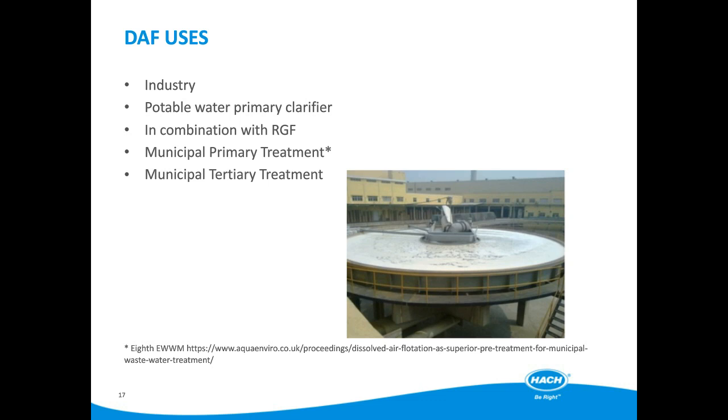During this latter trial, several arrangements were tried, initially with the DAF located after the primary settling tank, and then with the DAF receiving screened sewage. Other options were operating the DAF on air only, and then adding coagulant and polymer. The stated high removal rate of total phosphorus is not surprising given the combination of the solids removal rate and the addition of ferric chloride, which would chemically react with any soluble phosphorus present. But more information on this is available at the web address shown on this slide.